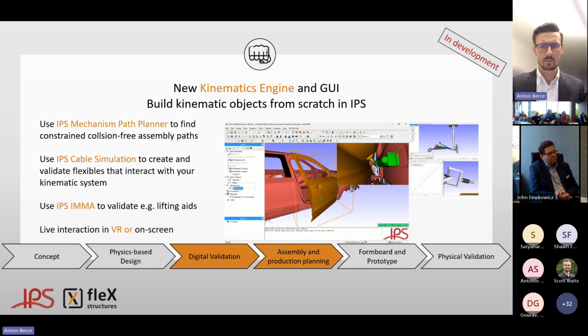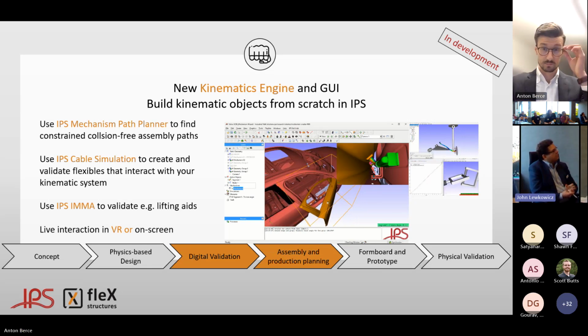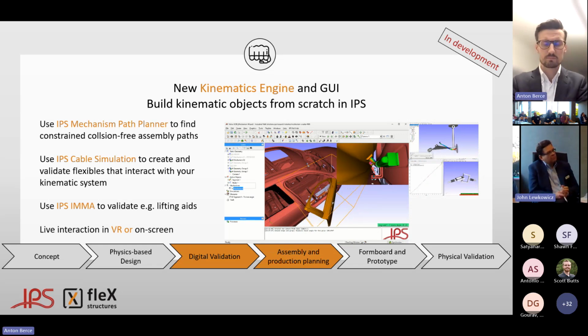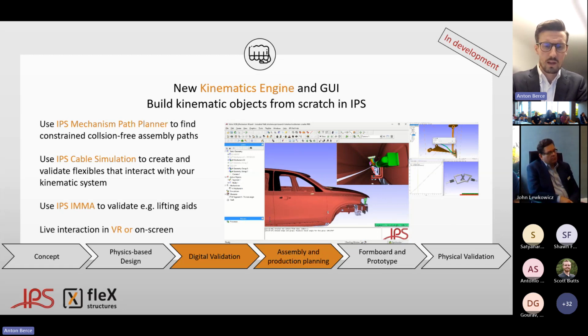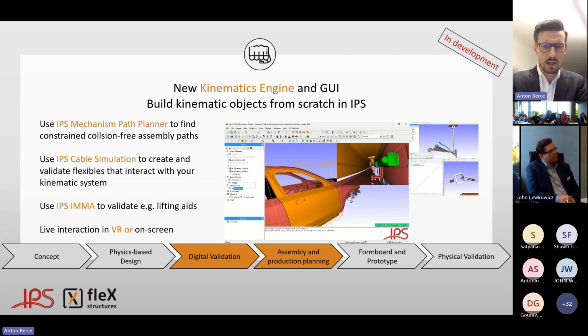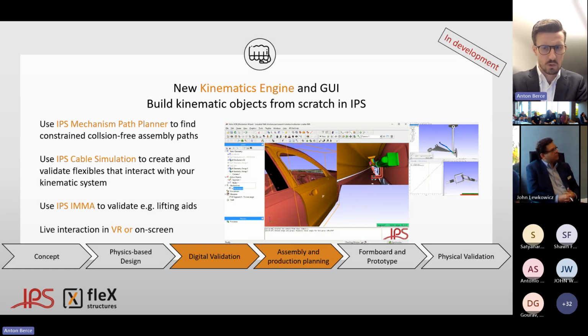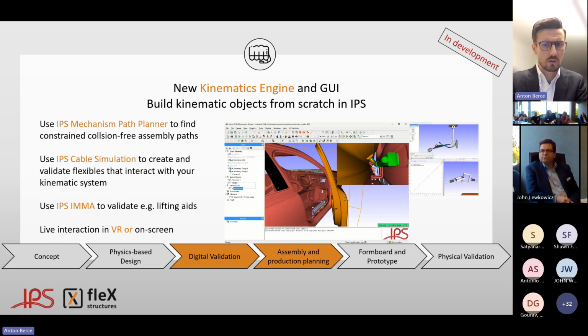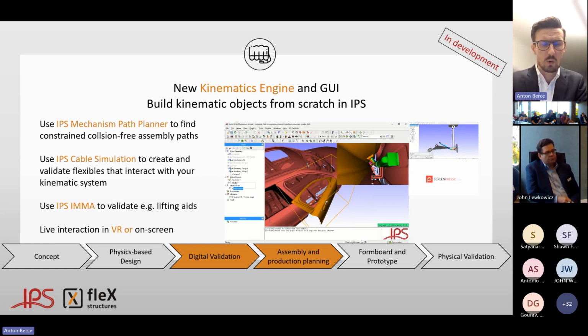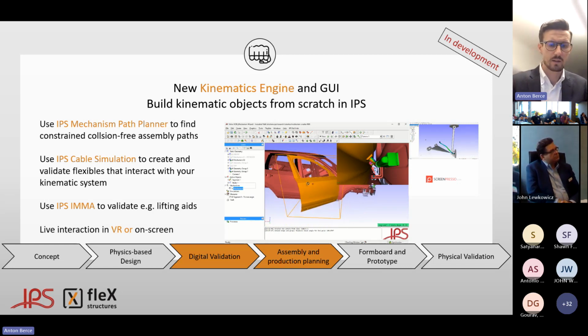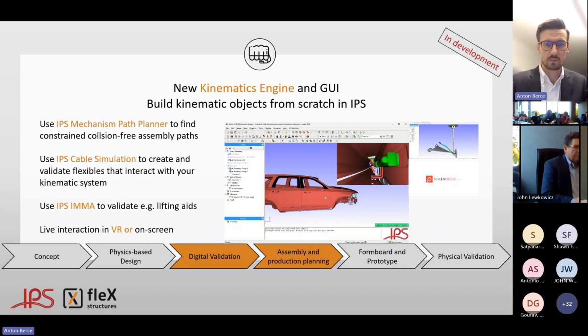And then to add to this question, and I believe we talked about this when we met in Germany, is there going to be a capability to create more complex kinematics like 4-bar links and things like that? In the first version, you will have only prismatic and revolute joints, but we will expand it in the release after, or at least very soon after, to ball joints and all different kinds of joints, so that you should be able to, in principle, build complete suspension systems with this.